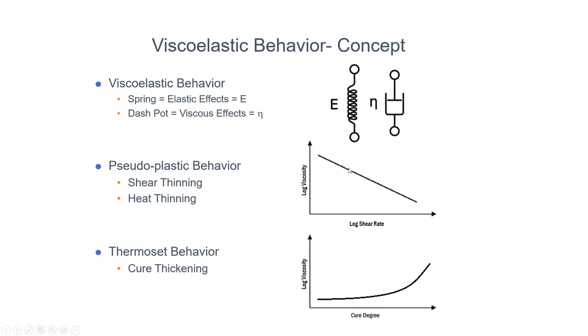Now, the slope of the curve, the height of the curve, those all change depending on material. The cure system itself changes over time, because what we do get with rubber is bin aging. So this curve will actually, because of the reactive chemistries in the rubber, change somewhat depending on how long it's been since the material was mixed. And then, of course, there's lot-to-lot variation and a bunch of other things. And that's what certain rheometers are really good at: the QC and the cure degree behavior, and understanding that over the course of time and lot-to-lot variation.